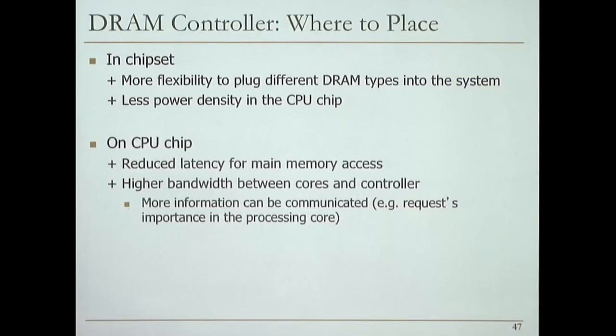Okay, so the memory controller is not in the same chip as DRAM. No, the first option. No. That's right. No, that's still not the case. Yes, that would be one of the other cases. Yeah, a better case perhaps. But the memory controller has so much functionality that it's not compatible with the DRAM process, the capacitor-based process.